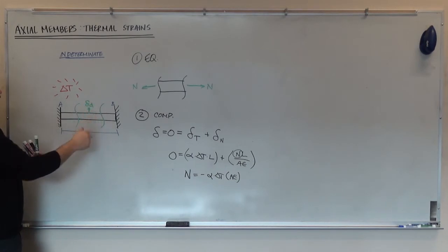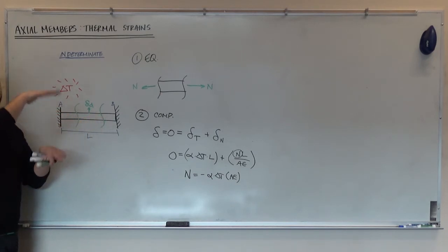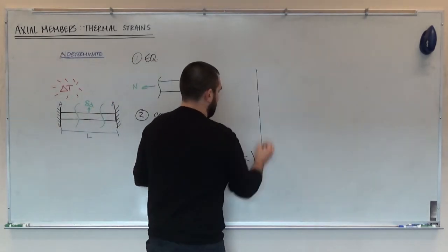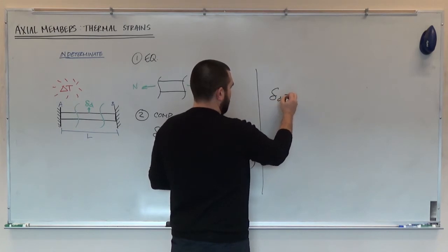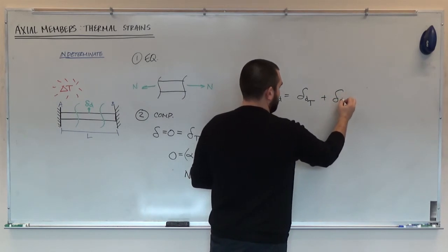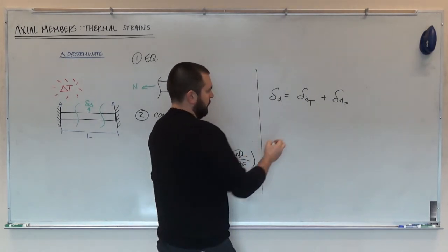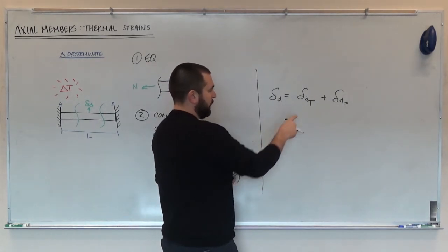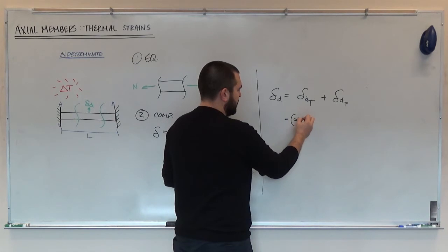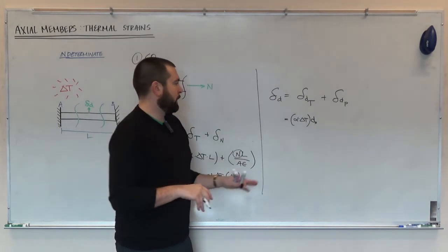And so in this case, transversely, the temperature's, let's say, increasing. That'll make it wider. And the column's in compression, which is going to make it wider in the transverse direction as well. And so in that case, just looking at the width, delta D equals some change in the width due to the thermal effects plus some change in the width due to the force-based effects. I'll say P or N, it would be the same thing. And we had just had this up previously. The change in width due to a change in temperature is simply equal to the thermal strain, alpha times delta T, times the original dimension, in this case the width, plus,